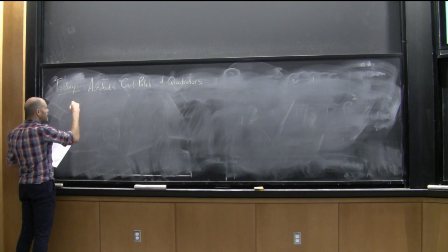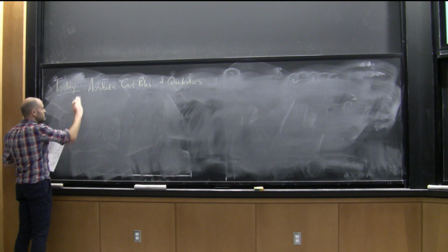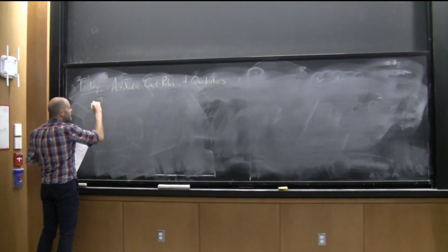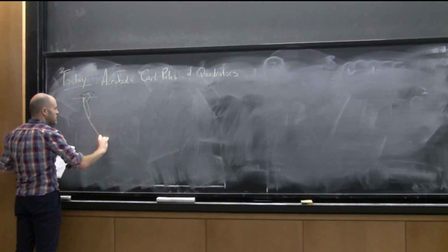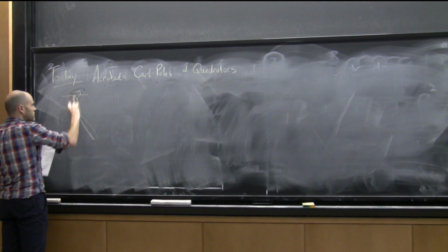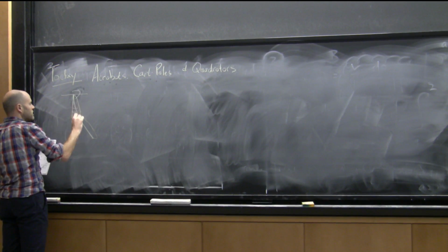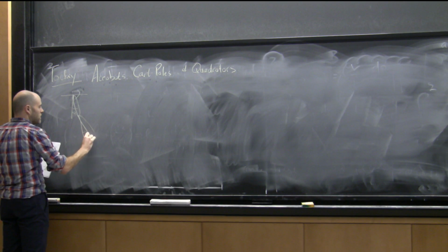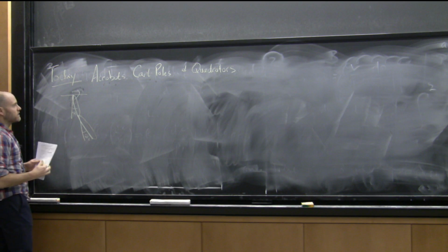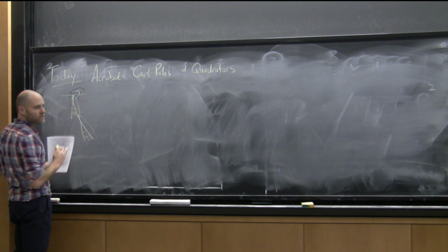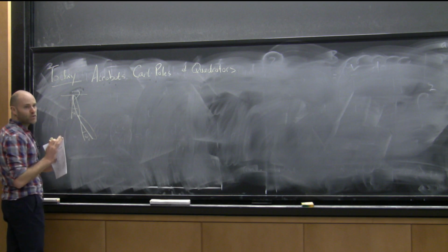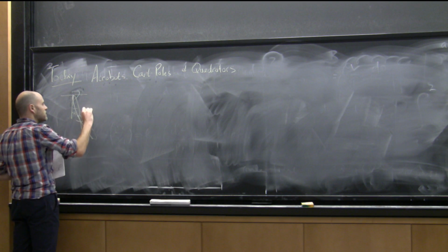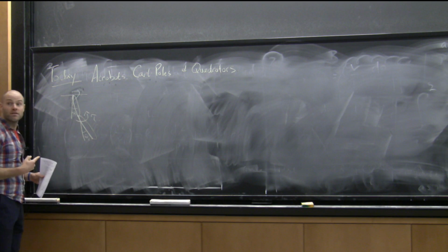There's the Acrobot. I will tell you what it is in a second. Well, let me do it now. So the Acrobot is a two-link manipulator, theta 1, theta 2, just like we did in the first class. It's got inertia along its rods instead of just a point mass. The only thing that makes the Acrobot special is that it's got a torque at the elbow, but nothing at the shoulder.